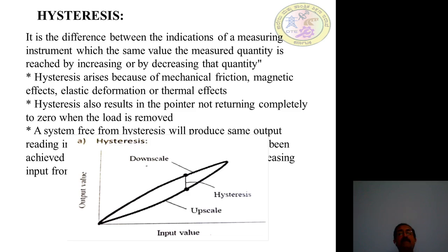So it is one of the important terms. While selecting the instrument and also while starting the instrument, you have to set the instrument or pointer to 0. Otherwise we will end up with some error.